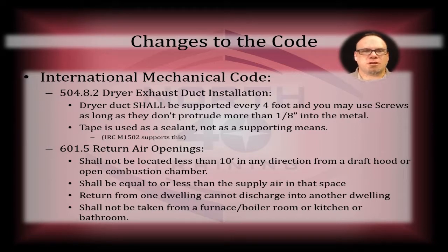If you're using it on a flue pipe so that the flue pipe is sealed, is your tape listed for sealing flue gas, or even for the temperature that the flue is going to be operating at? Right? Those are things to think about. Real life scenarios there.